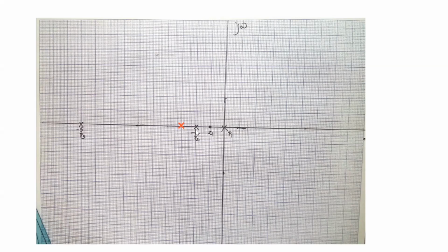Okay, so let this be the region of root locus. This is Z. From here to here it is a region of root locus, whereas from minus 1 to minus 1.5 is not a region of root locus, because we get an even number of poles and zeros. Then from here onwards again it becomes a region of root locus. After minus 5 it is not a region of root locus.